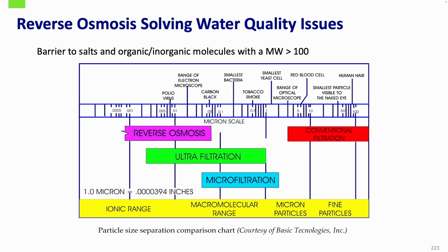In the state of Florida, the membrane technologies, reverse osmosis. When I talk about reverse osmosis, I also include nanofiltration. So nanofiltration, brackish water, seawater are essentially a reverse osmosis process. But they use that in the state of Florida because there's a lot of organics in the groundwater as well as hardness. And then now they're addressing the emerging contaminants also with it.